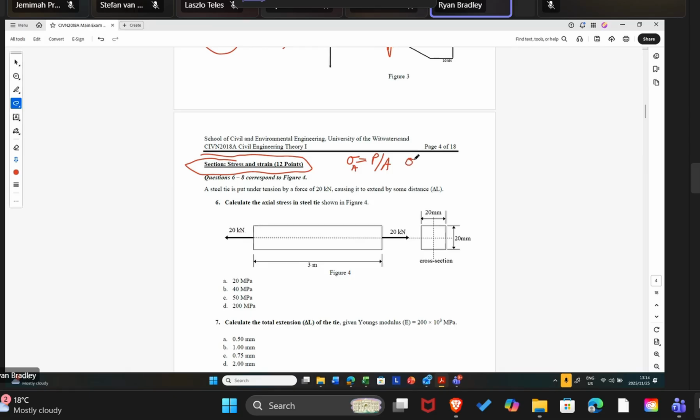We have the bending stress, which, if you recall, is the bending moment multiplied by this term y over I. This y over I is a geometric parameter of the section. Remember, y is the distance from the center to the edge, and I is the geometric stiffness. How stiff geometrically is the section? So to convert a bending moment into a stress, we multiply the moment by y over I.